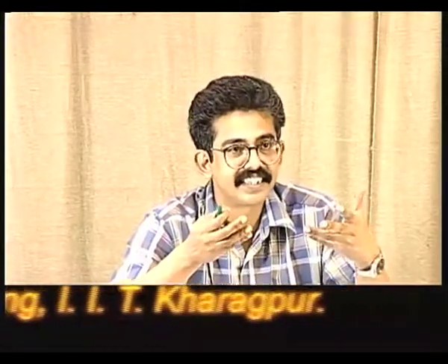It sometimes happens that the situation changes. Suppose now you have one kind of noise statistics, after 2 seconds you have another kind of noise statistics. So it's not possible to have a constant set of optimal Wiener filter coefficients, because things are going to change, and you cannot pre-compute them. So in such a situation, you also need a scheme which will continuously track these changes in the data and will always produce coefficients which are going to be good, if not optimal. If things do not change, they will slowly approach optimal. If things change, they will at least track the change, right? This is the best that you can hope for.